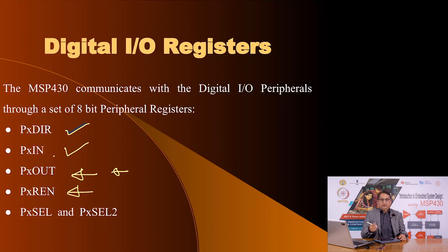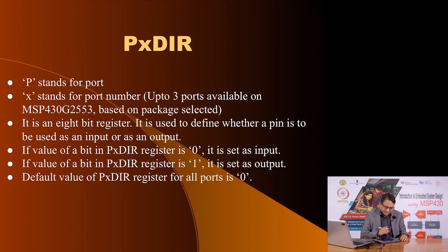And then, whether this pin is going to function as an input output pin, or take the alternative functions associated with this pin, will be determined by writing appropriate bits into the select and select 2 bits. So, this is the sequence of operation that we have to perform, and let us see how we do that.